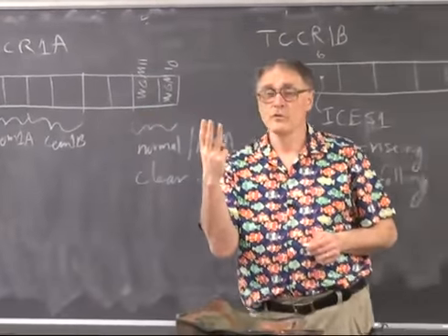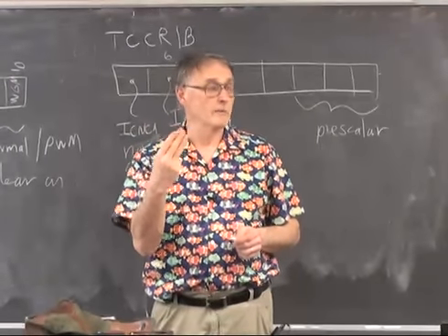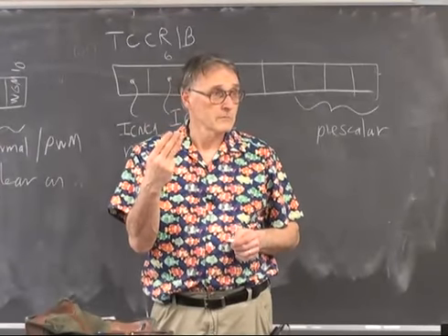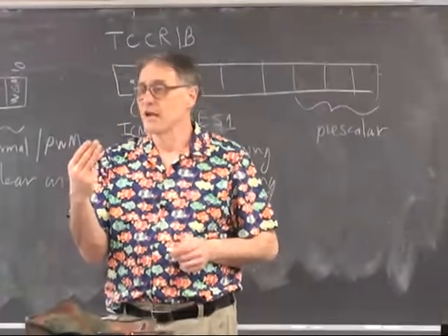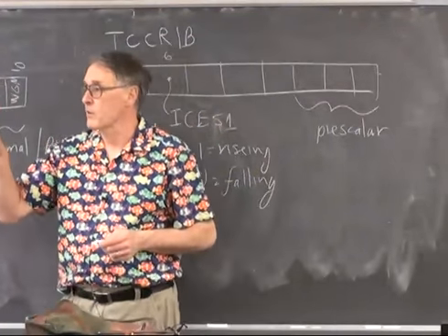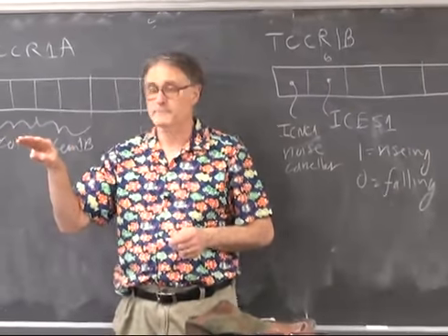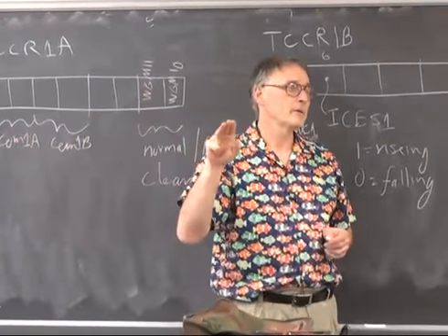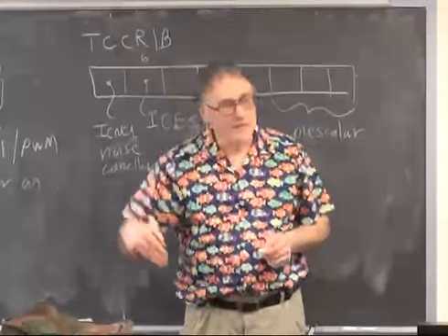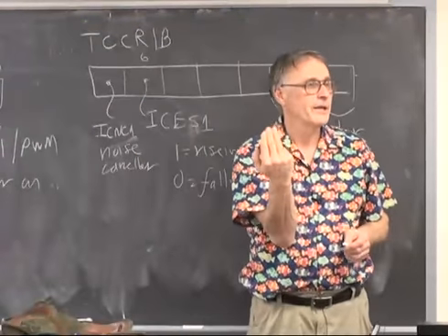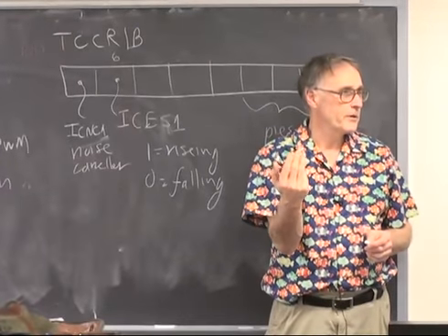And timer 2 is set up to produce the square wave that we're going to measure with timer 1. And so some of you probably used the timer 2 code to generate a square wave for the beeping sound in Lab 1. And what we want to talk about now is feeding that square wave back into timer 1 to measure its period.